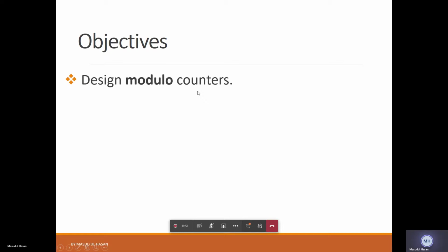Okay, now what is this third input of the AND gate? This is connected with CE. And why is it connected to CE? If you just imagine, this CEO is connected to the CE of the next counter, if we want to make a bigger counter, with another digit, for example.